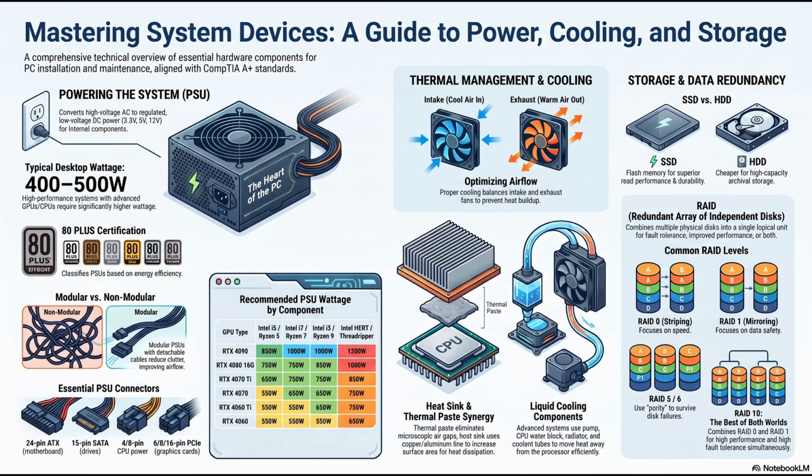And I noticed in the source material there's a fascinating physical artifact of this process tied to geography. The voltage switch. Most modern power supplies are auto-switching, meaning they detect the incoming voltage and adjust automatically. But slightly older or budget models have this tiny manual red switch on the back. The infamous voltage selector switch. It looks so harmless. It really does, but it's crucial. In North America, the standard wall outlet pushes about 115 to 120 volts.